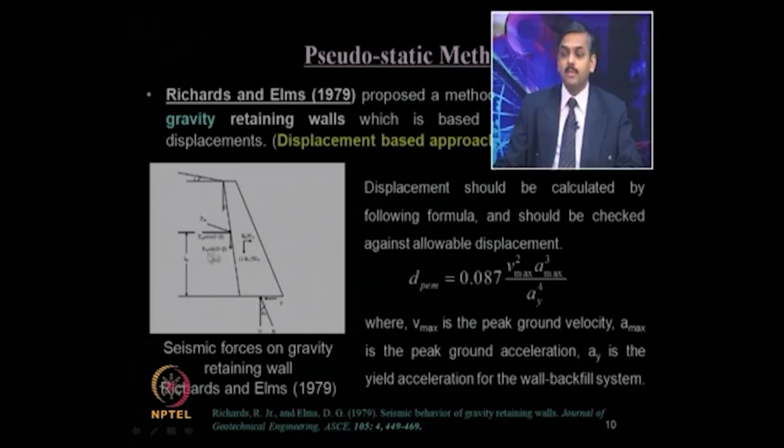The disturbing force is the horizontal component of the seismic active earth pressure and the seismic inertia of the wall, which cause the disturbance or tend to make the wall move in this direction. What are the stabilizing forces? The frictional force, which can be computed as tan of this angle times the normal reaction. What will be the normal reaction? If you do the vertical equilibrium, the normal reaction equals the weight of the wall and the vertical component of the pressure, which helps to find it out.